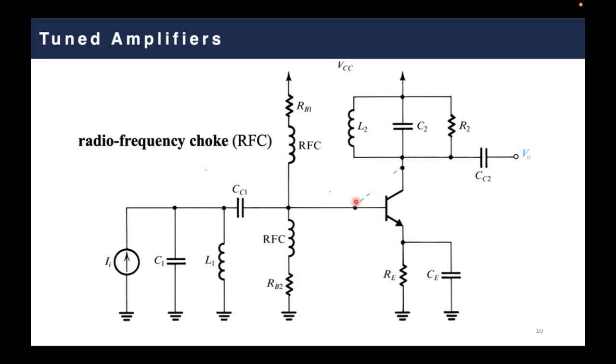In the active mode, if you remember, my dear students, we are acting toward having the base emitter junction to be forward. This simply happens by DC biasing this base terminal to be 0.7, making this base emitter junction forward. Alternatively, we act to have the base collector junction reversed.